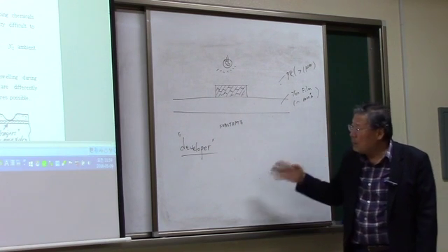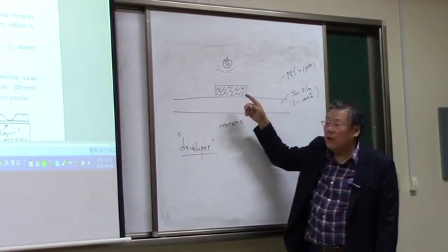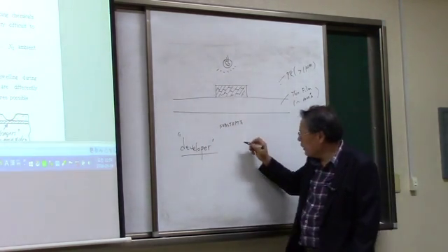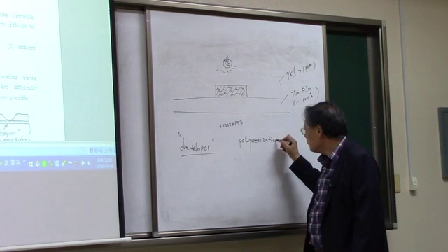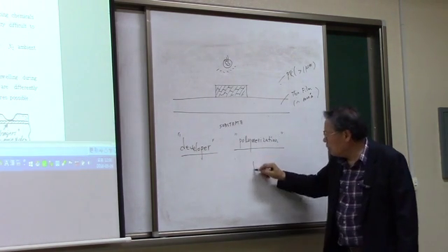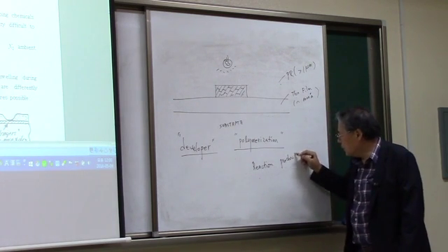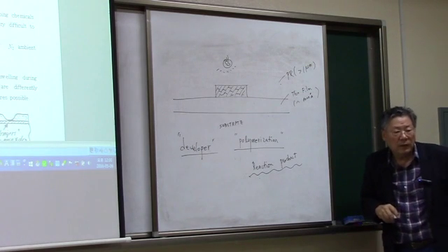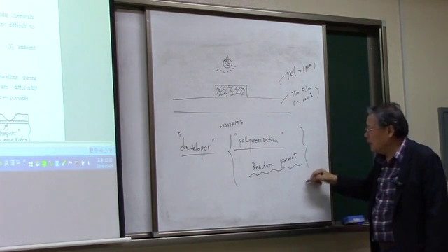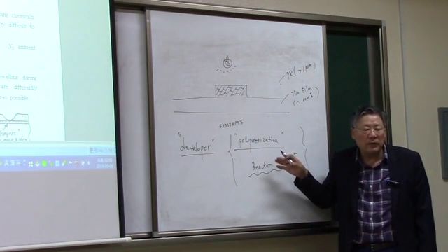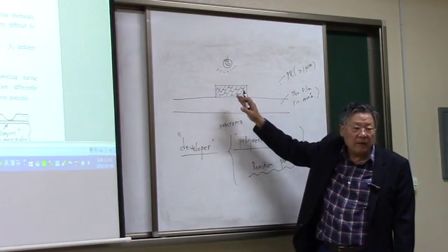Okay. Now the problem with the negative photoresist is that this part where the reaction, polymerization, happens is a kind of a reaction product, okay? This reaction product is important. So if anything happens in this reaction, polymerization, then it is going to ruin the resolution of the pattern.